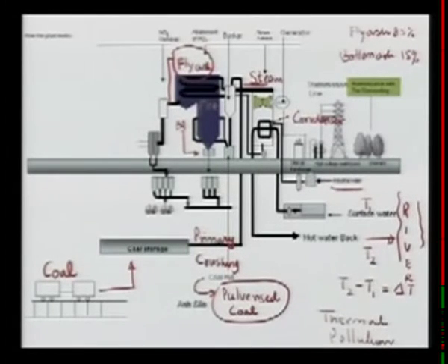Apart from the ash, you will recall from the combustion process that some NO2 is also significant from the air pollution point of view. It is NO or NO2. In fact, it's mostly the NO, so we should really call this NOx. NOx is also emitted, and the first thing we do even before fly ash is that NOx is controlled, and the process of control is what we call SCR, selective catalytic reduction, that we will see a little later when we talk about the control.